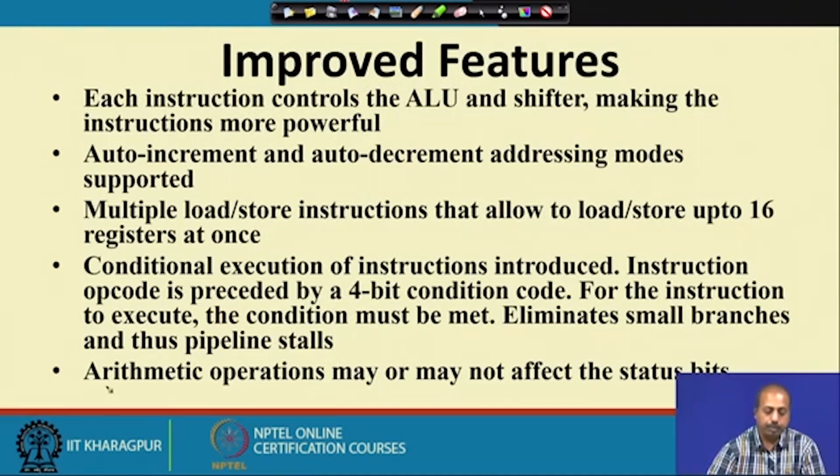The last point in this slide is that arithmetic operations may or may not affect the status bits. Normally, in other processors, arithmetic operations affect the status bits, like carry, overflow, the PSW bits. But here we have two variants of every instruction.